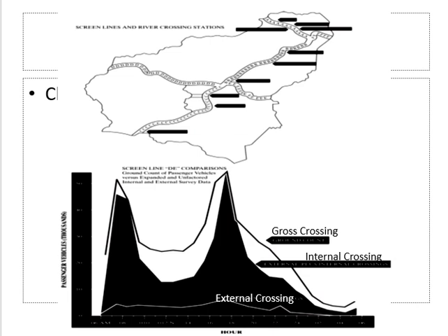If you have 1000 values, out of those 1000 values, these should be like 800, 900, something like this. If they are less and the others are more, then you have a problem. You did not select the area properly. You are doing the survey for an area where people are not going. You get my point? So a screen line should be between 2 important areas where people have more demand.